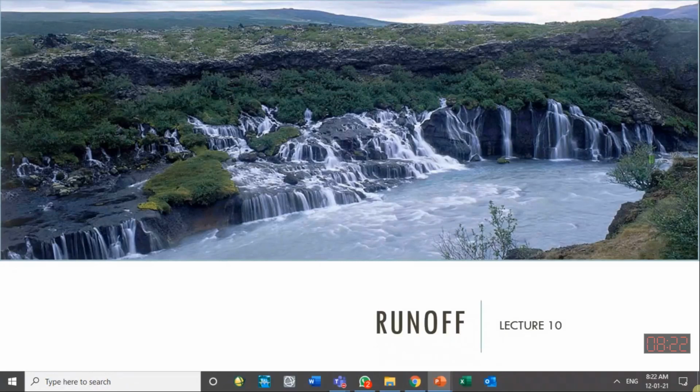It can come out of the ground. In case of groundwater, sometimes we have pressurized springs, but that is because of the higher pressure at some place in the aquifer. Aquifer is the soil layer containing water under the ground. You will use this word in groundwater hydrology, which is one part of hydrology. So in groundwater, sometimes we have flow against gravity, but on the surface, we always have flow towards the downslope or downhill. From higher elevation, it will go to lower elevation.